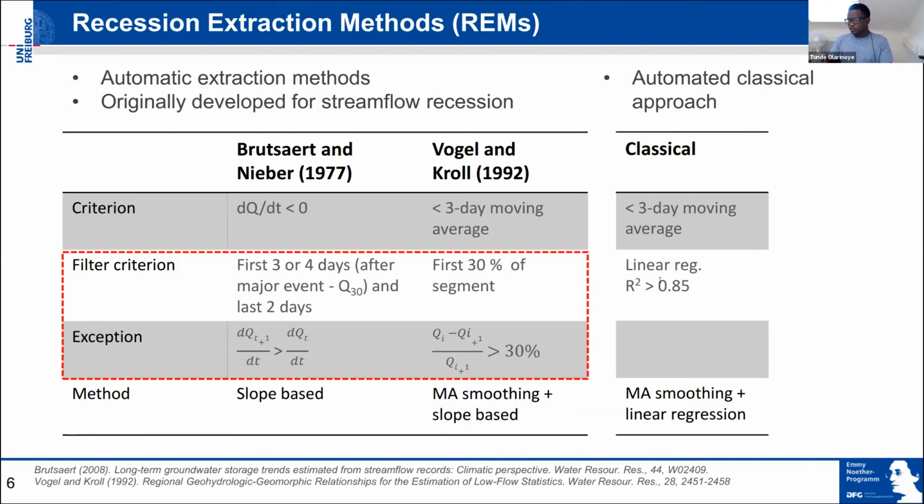So if the R square is less than 0.5, then we remove the first point, then fit to the rest of the points. If it's still less than 0.5, we remove the second point and fit the rest of the points till we have an R square of 0.5, where we consider we have a linear model, which is more representative of having a base flow.